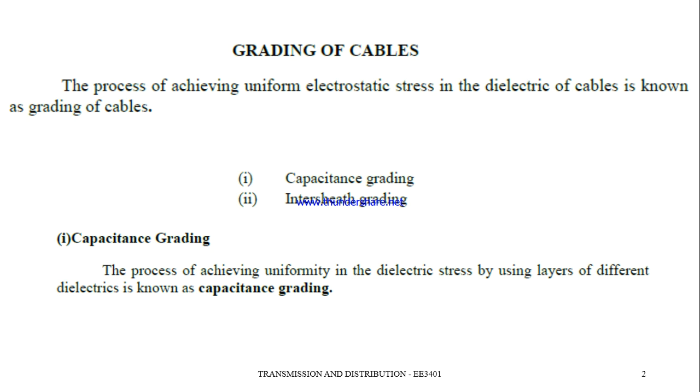In order to achieve a uniform electrostatic stress, we apply this grading process. Why do we need uniform electrostatic stress? Non-uniformity may cause breakdown of the insulation very easily. If the insulation breaks down, the conductor will be exposed to the outer surface or to the ground level, and there may occur leakage of current. In order to avoid this, grading of cable is essential.